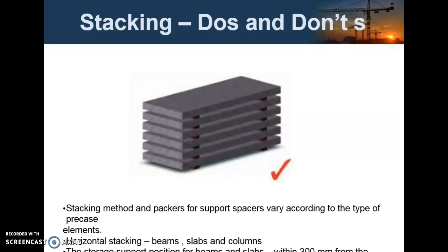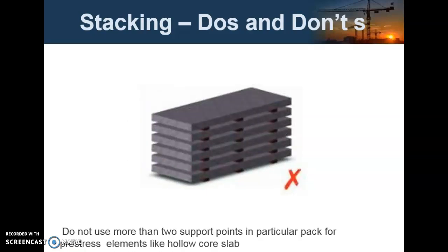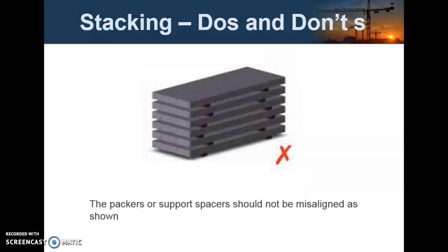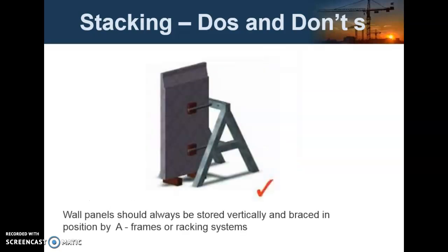It is the horizontal stacking. It is the wrong method of stacking. There are more than 2 supports for the horizontal component. It is also a wrong stacking method. There is non-uniform support for the horizontal stacking. Wall panels should be stored vertically like a rack system.